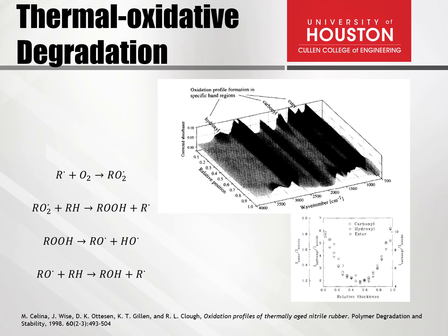One of the most studied degradation mechanisms is thermo-oxidative degradation. Oxidants attack the cross-link sites or backbones, which is described as chain scission. Some researchers use FTIR to study thermo-oxidative degradation, based on the change of relative ratio of peak height of chemically active functional groups to inactive groups, and therefore we can semi-quantitatively identify the progression of thermo-oxidative degradation.